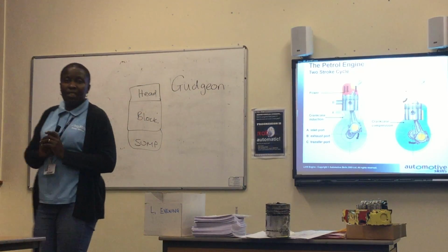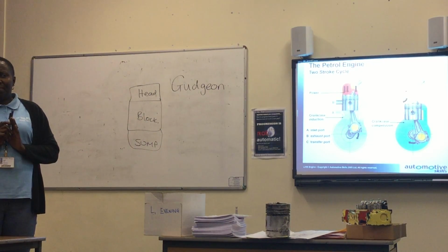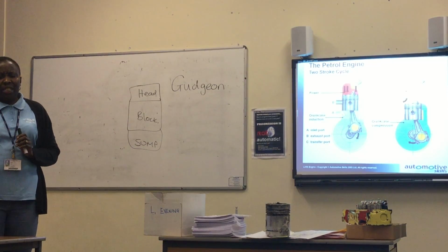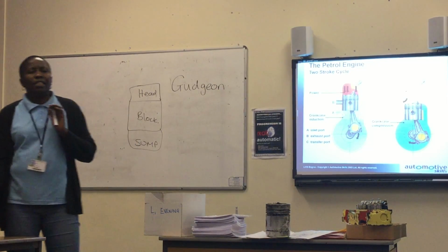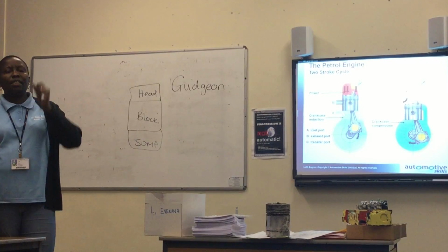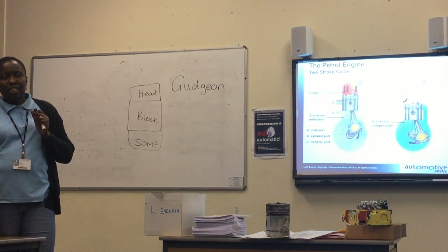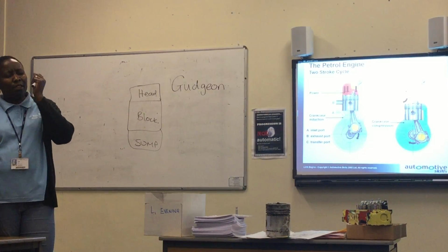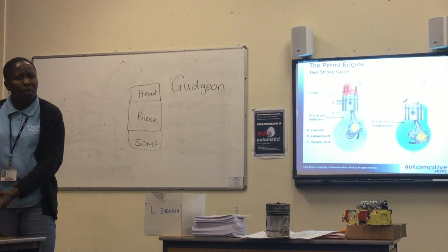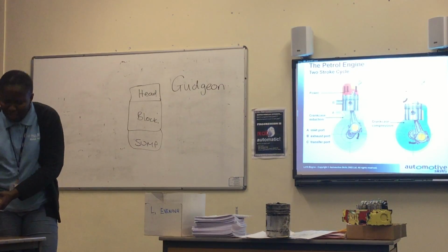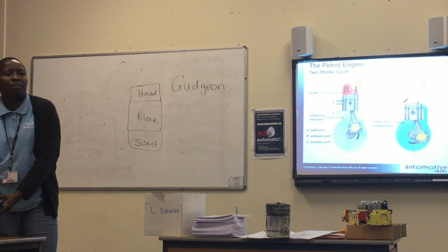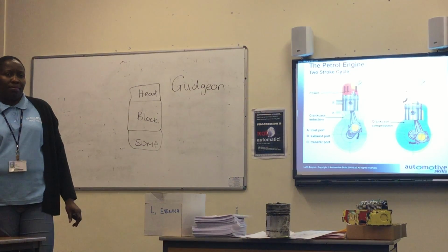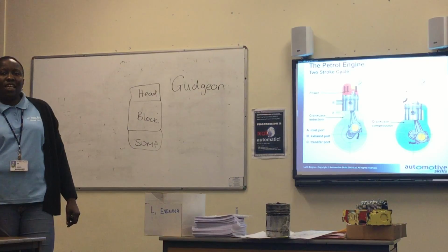So that's the connection. Are we clear on the piston? At the end of the day, the purpose of the piston is that it acts as a gas-tight plunger inside the cylinder, and it also transfers the force. Remember, during the power stroke, it transfers that force through the connecting rod to the crankshaft. Happy with what the piston does or why you need one in the engine?